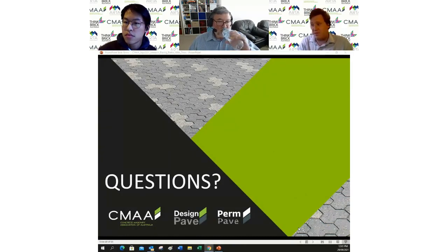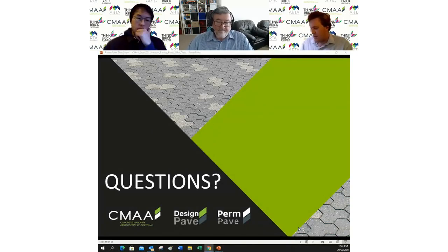But starting from the top, the first question I think is from Ben. And he says, are shrink swell movements of high plasticity subgrades an issue with permeable pavements on an uncompacted subgrade? No, we haven't found any problems with them as yet. But again, I'd like to see some more research.